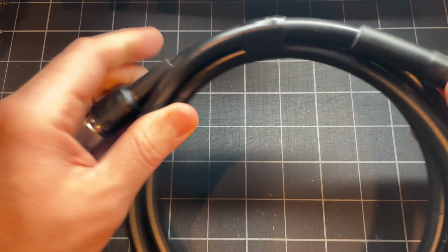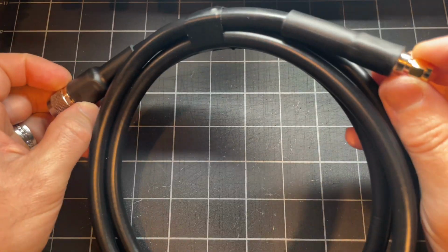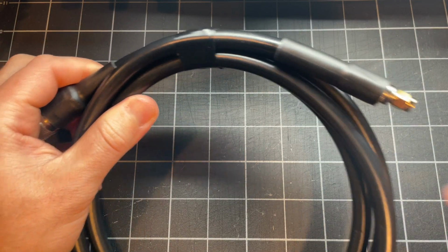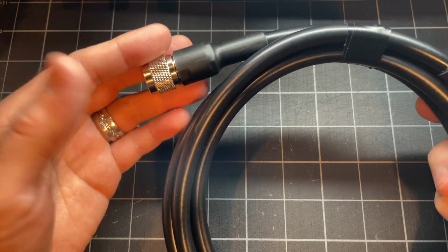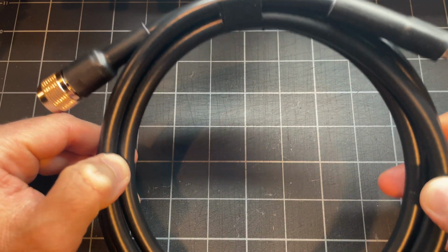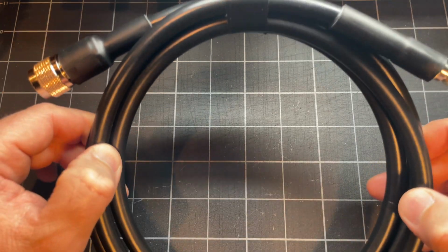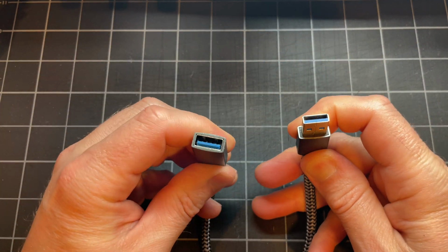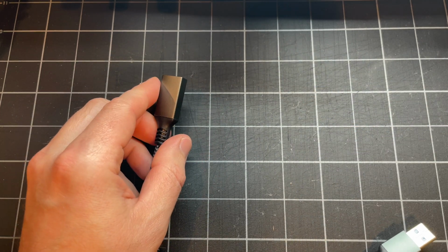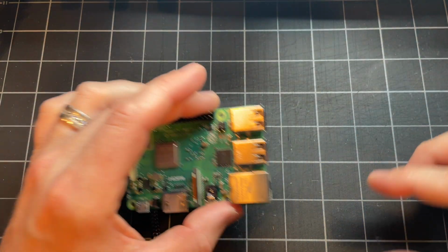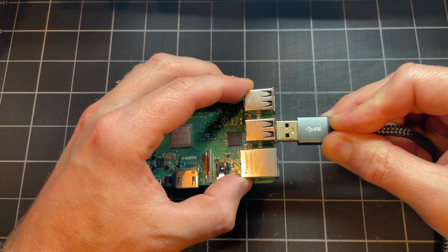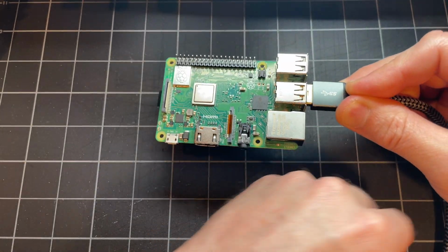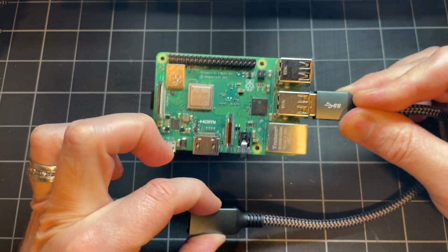Lastly here, we have a coax cable. Because I went with the N connector antenna, I've got the SMA on one end to go to the dongle, and on the other end I have an N connector to go to the antenna. I went with a very short piece of coax to keep it as short as possible and eliminate as much line loss as possible. An optional thing to consider is just a USB extension cable. Because that dongle will be sticking out of the Raspberry Pi, I elected to go with an extension cable to let me extend that out and not put as much strain on the connector there. So I'm going to go this route.